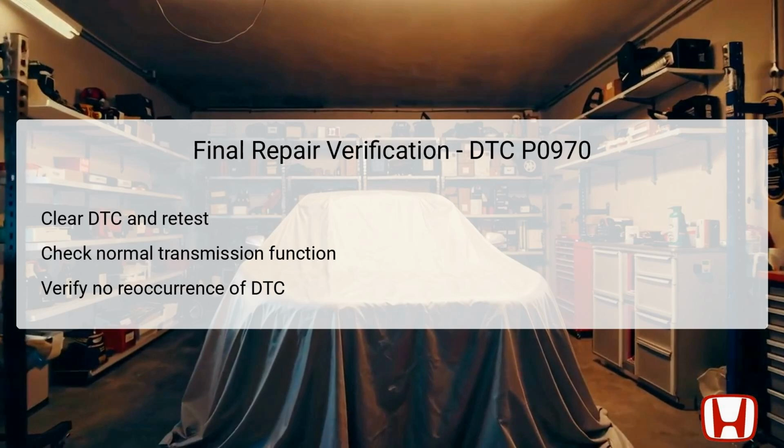After completing all necessary repairs, the final verification step is crucial to confirm the effectiveness of the troubleshooting and repair process. Start by clearing the DTC using the HDS tool once again, which allows you to reset the system for a new diagnostic check.